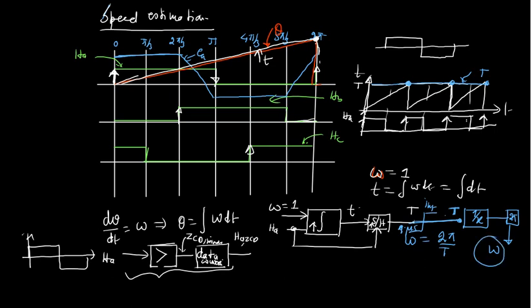But please remember that this omega is an electrical angular speed. So you have to convert it into mechanical speed. So what will be the mechanical speed? The electrical speed divided by the number of pole pairs. Suppose your machine is 4 pole pairs, so it is an 8 pole machine. If it is 16 poles, then what is the pole pair? It is 8. So in this way you can measure the mechanical speed.